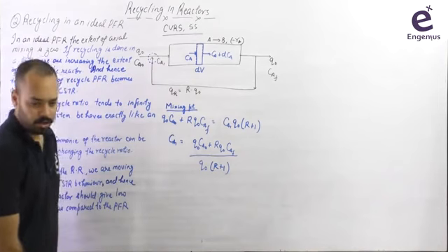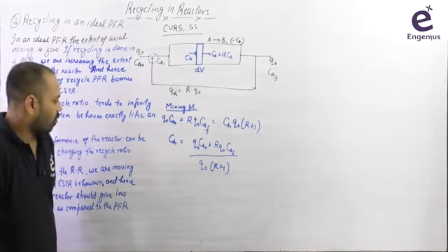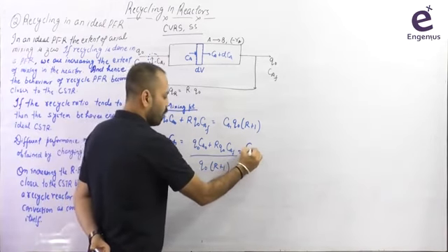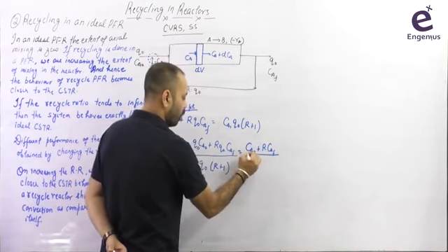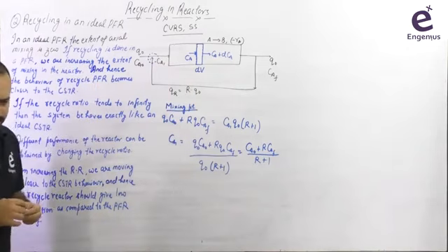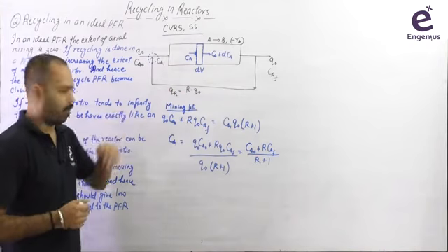It means the value is Ca naught plus R CAF divided by R plus 1. The volumetric flow rates are getting cancelled, so that is Ca naught plus R CAF divided by R plus 1. It is simple balance, simple mathematics.